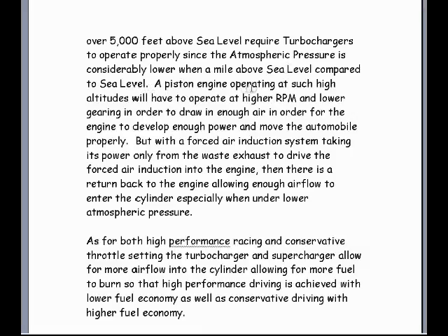A piston engine operating at such high altitudes will have to operate at higher RPM and lower gearing in order to draw in enough air for the engine to develop enough power and move the automobile properly. But with a forced air induction system taking its power only from the waste exhaust to drive the forced air induction into the engine, there is a return back to the engine, allowing enough airflow to enter the cylinder, especially under lower atmospheric pressure.